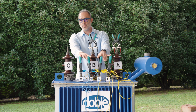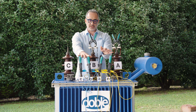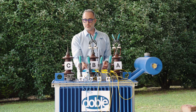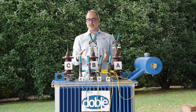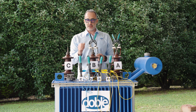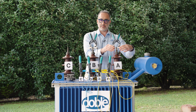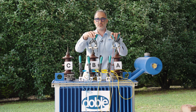There are some cases when the test is done in a different way, but for these purposes, the secondary side is short-circuited. In this case, I used 2 wires between phases. I could have used maybe 1, but the more wires you put, the better short-circuiting you do, the better the result will be. If you are doing this on a bigger transformer, I propose thick cables. The thicker, the better. So I short-circuited the secondary side, and now I'm going to generate AC voltage on the primary side. Phases A and B will be the first test. Let's do that.